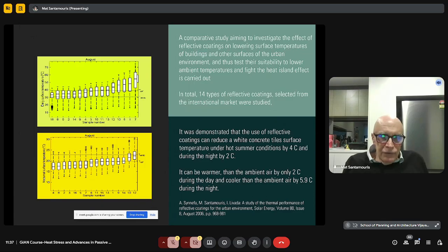You may ask me, why use low emittance materials? Low emittance materials are used for military reasons. For example, if you have a military building and you really want to cover the existence of this building, or you don't want what is happening in the building to be followed by the satellites. The satellites measure the infrared radiation sent by the surfaces, by the materials.